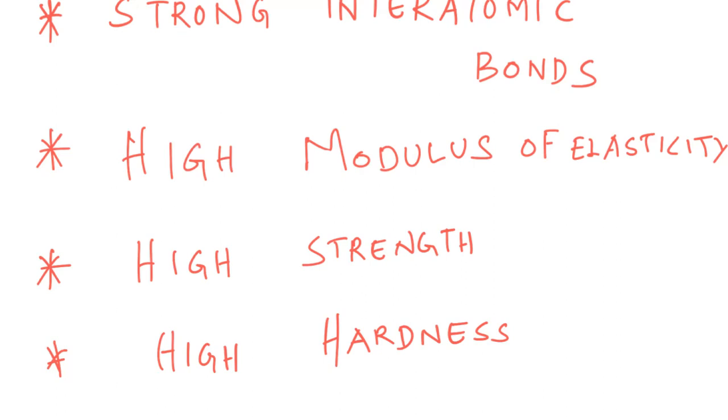Let me explain it this way. Let's say this is my stress strain diagram, and in this portion we have linear behavior. What happens in this portion is that the atomic bonds get stretched when you load the material, and the atomic bonds restore their initial unstretched position once you unload it. Since the bonds are very strong, Young's modulus is also quite high for these metals.